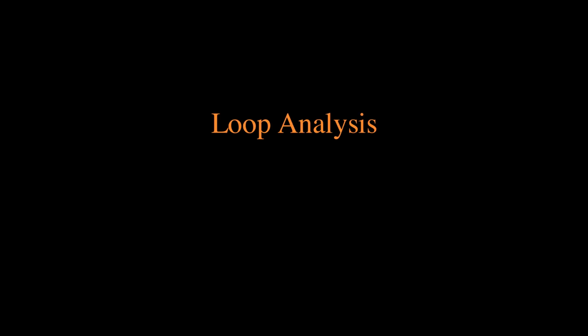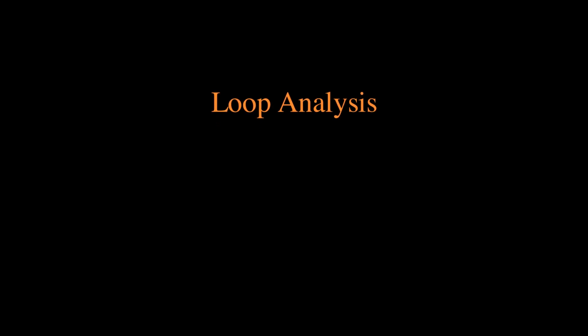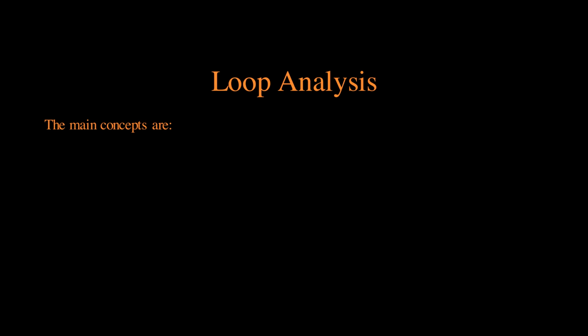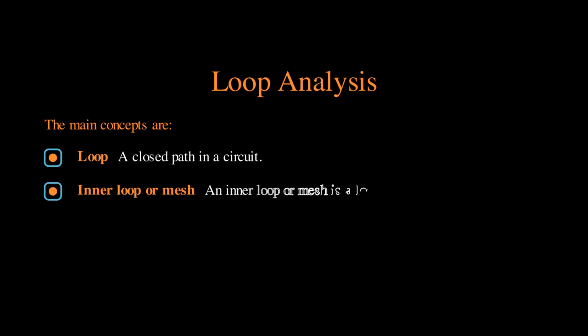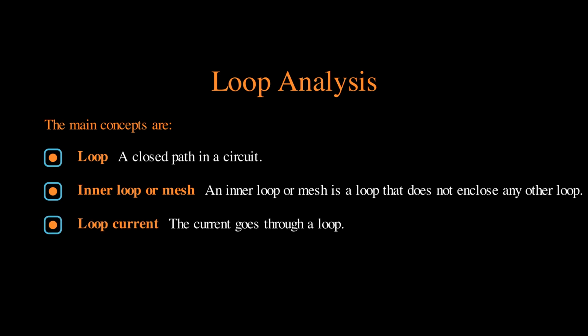In this video, we will learn loop analysis, a method to solve loop or mesh currents. The main concepts are as follows. Loop, a closed path in a circuit. Inner loop or mesh. An inner loop or mesh is a loop that does not enclose any other loop. Loop current. The current that goes through a loop.